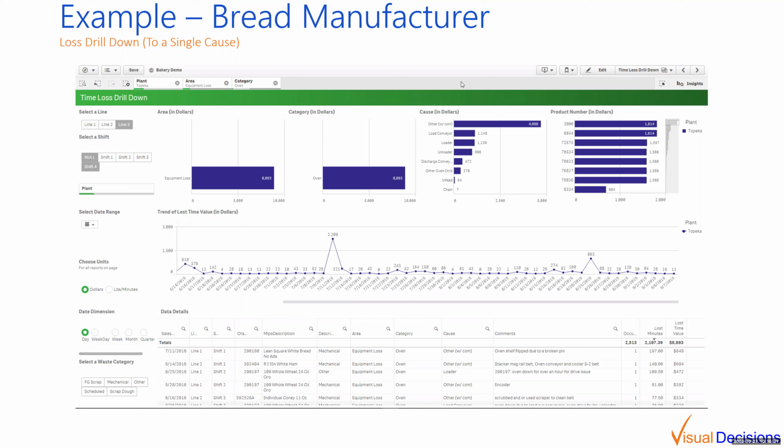We just put in a preventive maintenance program to inspect and replace the fatigue pins during an off shift. And just by having visibility to this, we were able to eliminate the single largest source of downtime and raise the OEE of that process by a significant amount just through that one change. And again, the change itself was very simple.